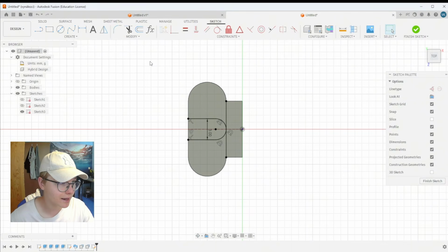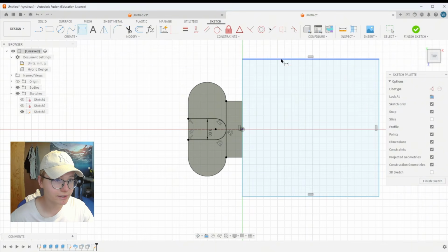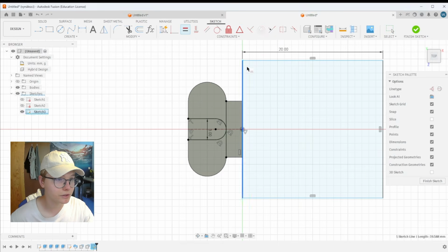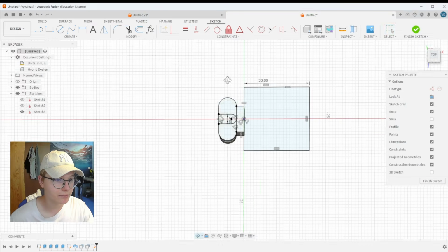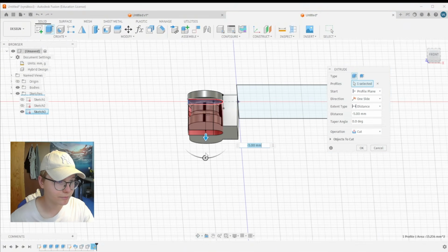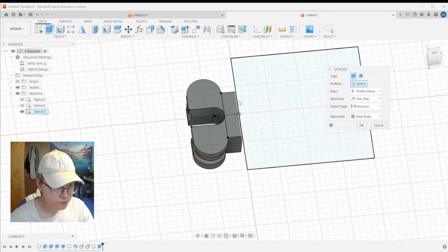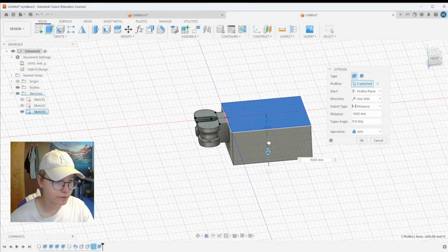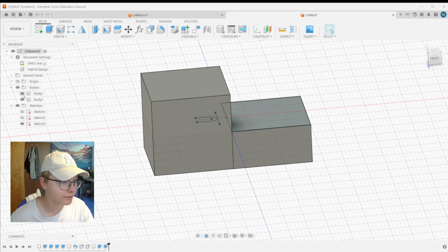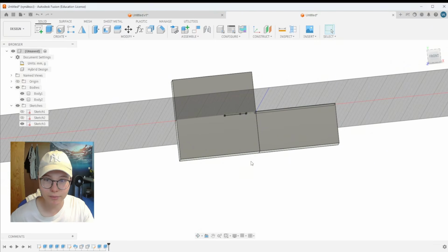I will be making the example square as I made before, exactly the same as before, so it's 20 millimeters, and the midpoint of this will go over here. That's all that I need to do, and then make both of the sides equal, just like this. Once that is done, I have all that I need from this sketch. Then cut this from the body, perfect, and then extrude this 10 millimeters down, just like this, so that it would fit with the first body. As you can see right now, it's perfectly aligned. That's exactly what I wanted to have.